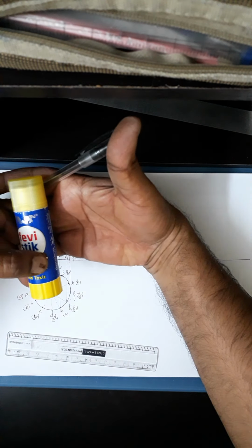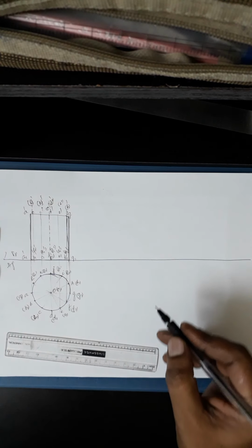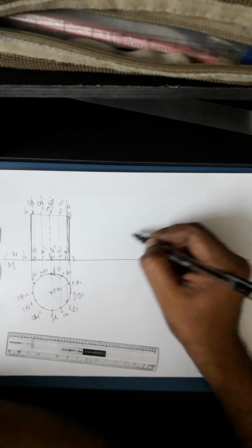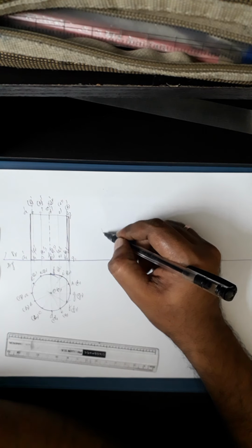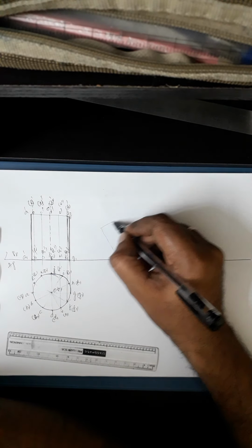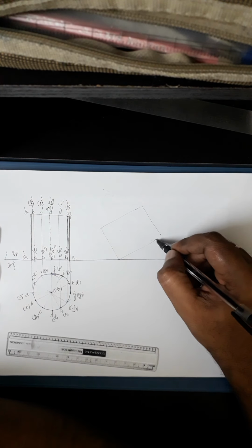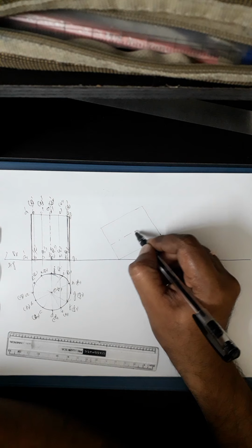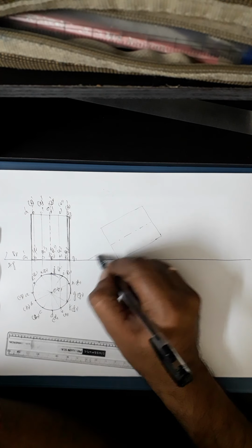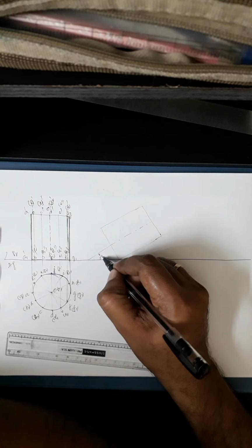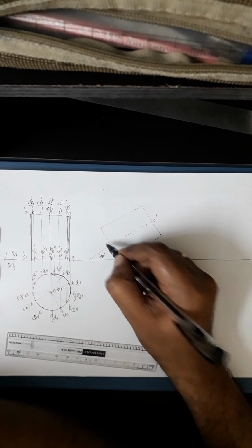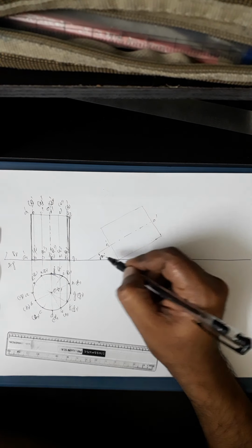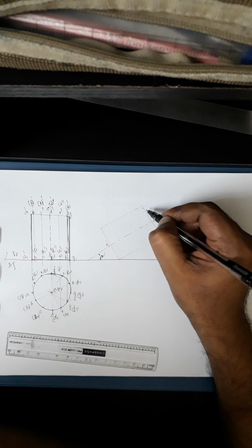Then when you project and bend, this is the position. He says the axis is inclined at 30 degrees to VP, so in the same way, inclining the base at 60 degrees, we'll incline the axis by 30 degrees, 90 minus that, right? Same view we have to redraw. See, if you take this as 60, this will be automatically inclined at 30 degrees, because the axis is inclined at 30 degrees. Just dimension only the axis, not the base. So then I'll mark the same view.